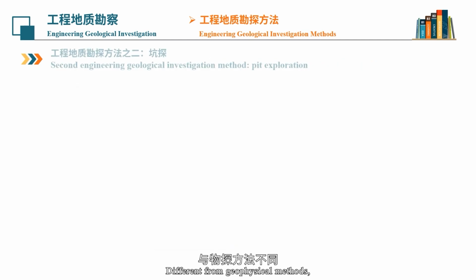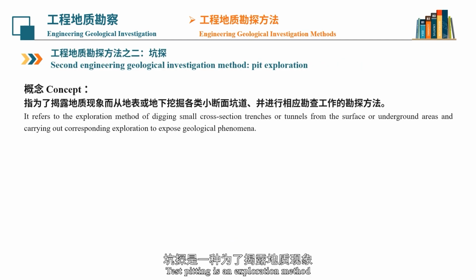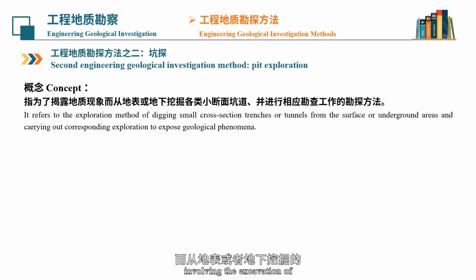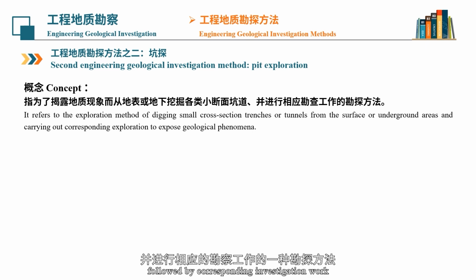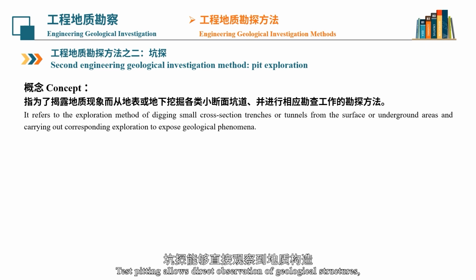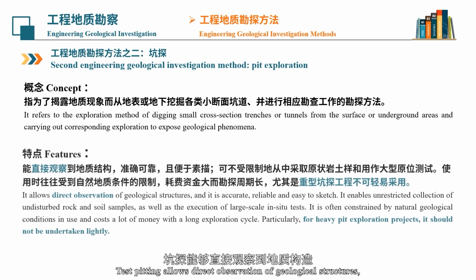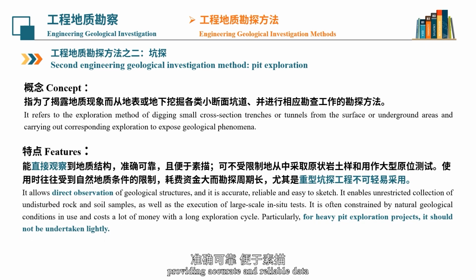Different from geophysical methods, test pitting is an exploration method involving the excavation of small cross-section trenches or tunnels from the surface or underground to expose geological features, followed by corresponding investigation work. Test pitting allows direct observation of geological structures, providing accurate and reliable data.